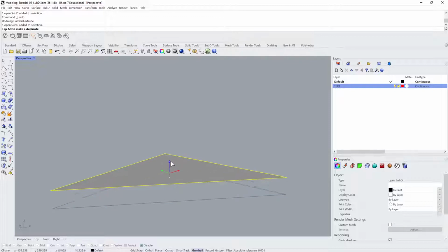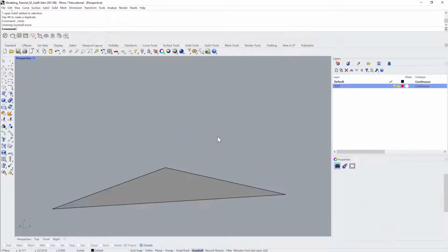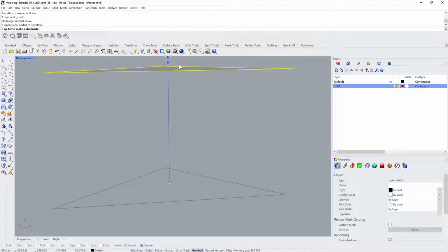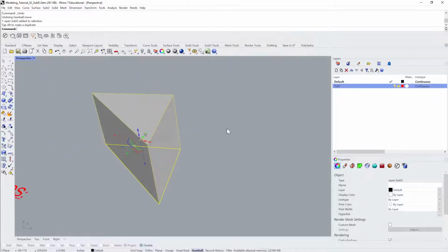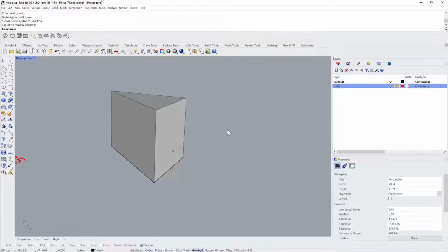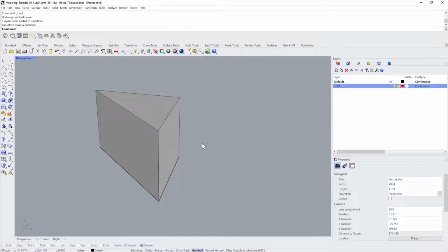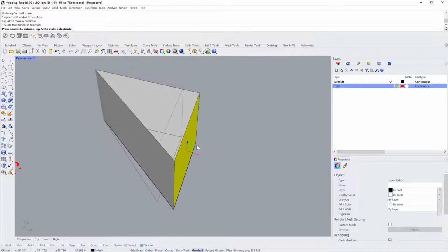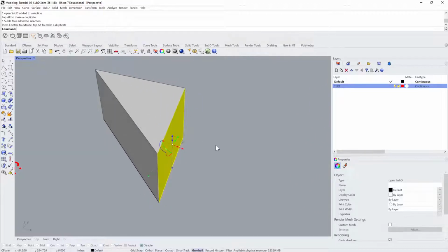Again, if I just grab the top of the arrow, I'm moving this thing up and down. If I grab the middle of the arrow where this dot is and pull up, now I've extruded this object. So I have just pulled that face and extruded it up. So this push and pull, on the one hand, refers to the fact that now I can Shift Control, select an individual face, and push and pull that around, but I could also extrude that face.